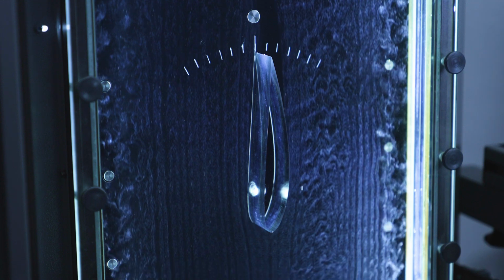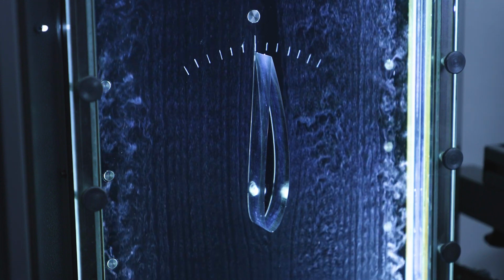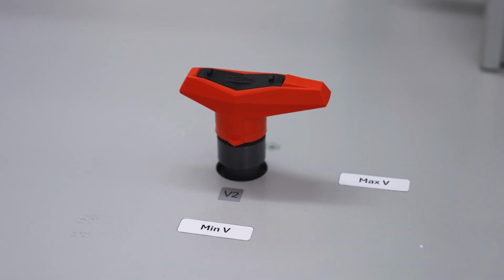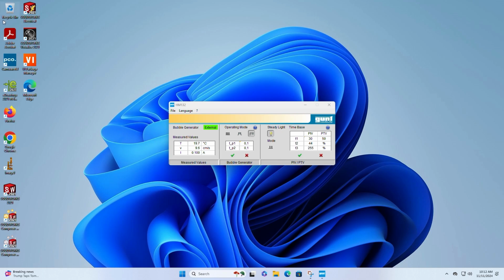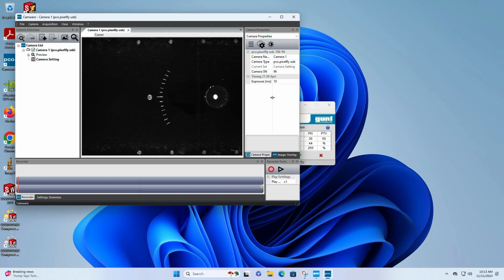Bubbles must be flowing along the chamber. If not, ask the instructor for help. If needed, the flow velocity can be adjusted by adjusting valve V2. You may start taking pictures or video of the flow field. Open the software CameraWare. The software should recognize the camera immediately. If not, notify the TA or instructor.